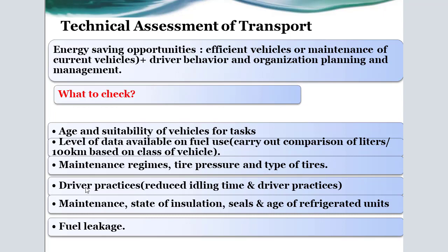Also check driver practices, such as reducing idling time and applying all the required information to reduce energy or fuel consumption, and also review the maintenance and state of installations, seals, and the age of the refrigerated units of transport vehicles, and also check the fuel leakage from tanks or the piping system of these vehicles, and so on.